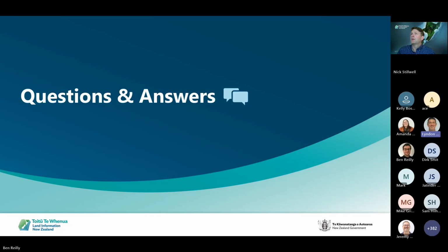Hi Paula. Good suggestions. I feel like this is a bit of a cop-out response, but it's the same as our previous responses. We've had to retain the existing line styles to maintain compatibility with legacy Landonline. So there's certainly no plans to add a calc line style, and we'd have to look carefully at that. There's not an Abutto line style, but as a workaround you could use the dashed line style and make it bold. I know some surveyors use that as a workaround. There's also the option to go back into define diagrams and add a freehand Abutto line in there.